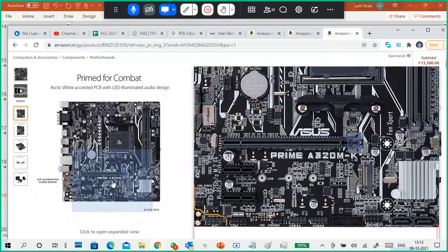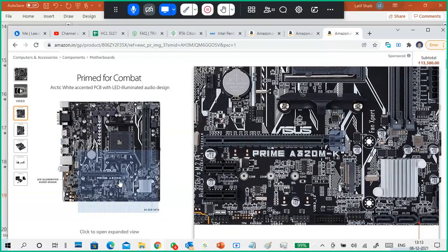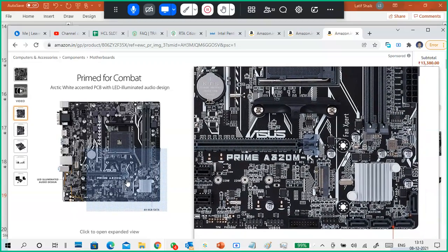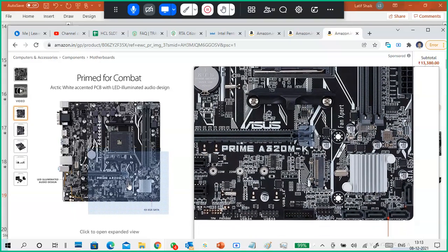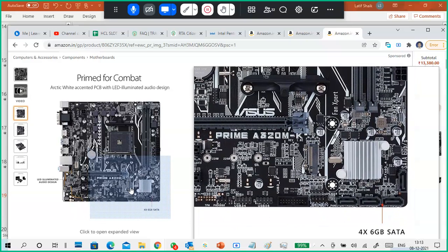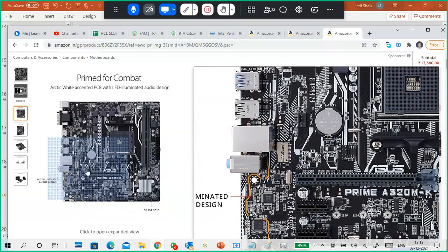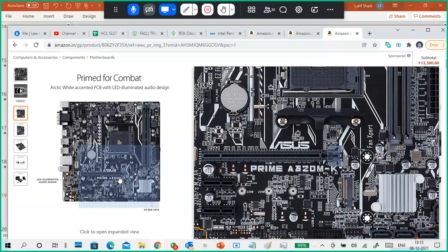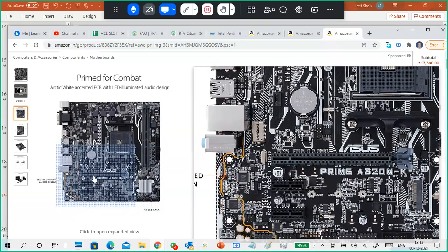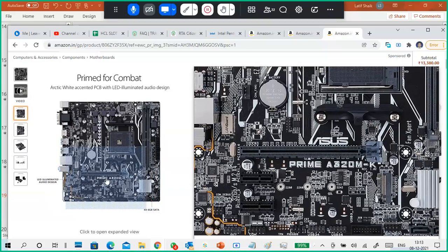Initially, I didn't understand because I only knew very old types of motherboards. I don't know the new motherboards. Last year, I purchased a new motherboard and got confused. I didn't get a display. I thought I connected it wrong, or maybe the motherboard or CPU was damaged. Finally I found it was not a problem; the problem was the graphic card. The CPU doesn't have any video memory, zero memory, so I compulsorily had to use a graphic card. No graphic card, no display.